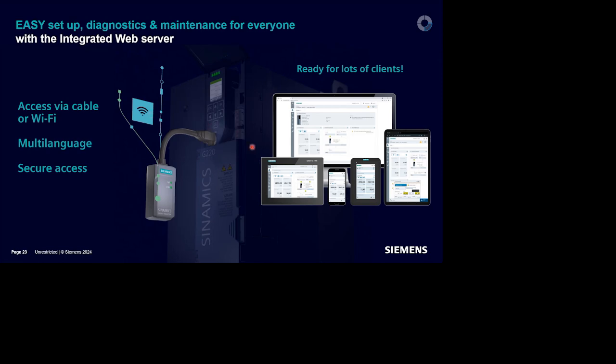For that, we have this accessory here, which is called the Sinamics Smart Adapter. And I know in the G120 family, we have the option module, the Smart Access. But the philosophy here is slightly different. With the Smart Access, we had the web server in this module. But in the Sinamics next generation, the web server is completely inside the drive. The only thing this Smart Adapter is doing is creating the Wi-Fi network. The main information is coming from the drive. And this has a lot of benefits.